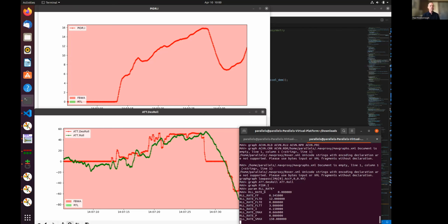Yeah. This was the first flight. And unfortunately, the pilot didn't have manual. Manual wasn't available as a mode. The plane got too far away, like lost orientation, switched it to RTL, and then it started to depart in roll, and RTL wasn't able to recover it. Of course, it didn't have attitude control, and it ended up destroying the aircraft.